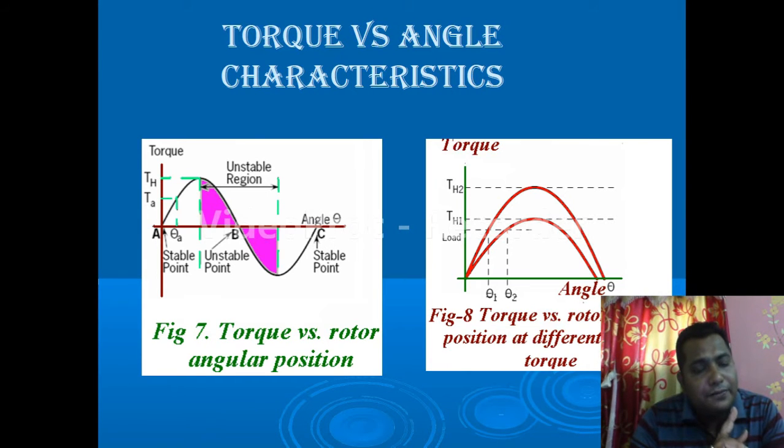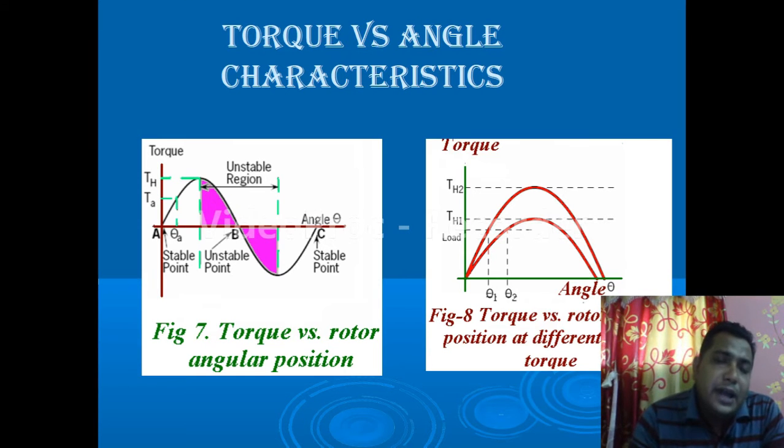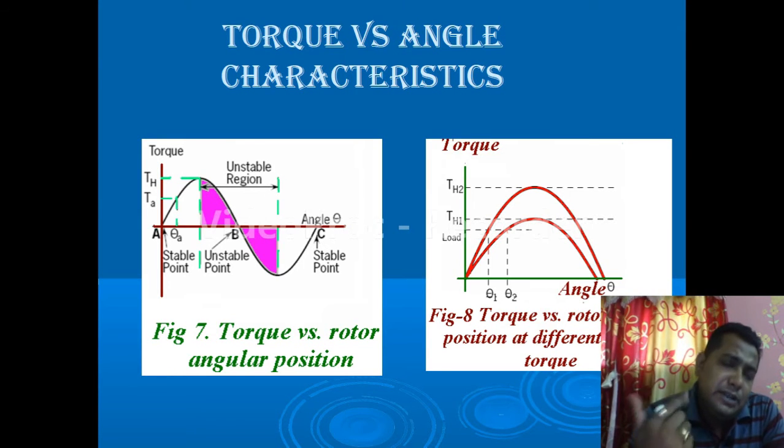So when the rotor starts rotating, just starts its motion, at that time it is stable. After it reaches its maximum angle, when it is reducing its angle, the rest torque is going to be reduced. That means with the increasing value of angle, the torque is not continuously increasing. After a certain point it is again decreasing. It will go to 0. Again, if we increase the angle value, it will increase, but in the negative direction, to the negative maximum.